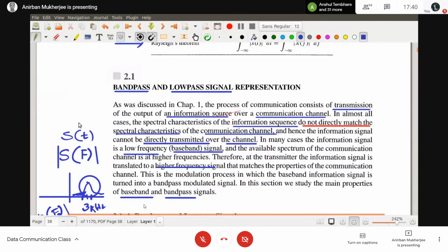If you take s(t) and do the Fourier transform, you get S(f), and most of the time you will get a complex value. Or do you always get real? So complex, how will you plot? Either you have to plot the magnitude mod S(f) versus F, and ideally when you plot, you plot in this way.